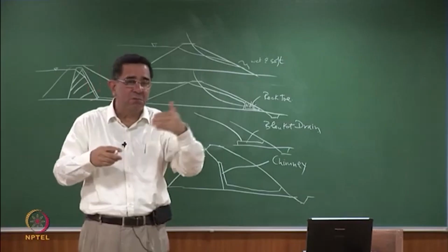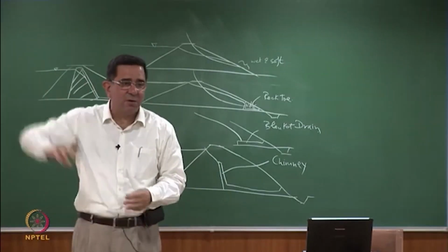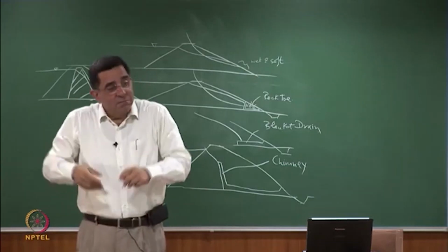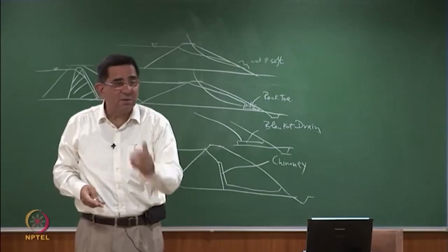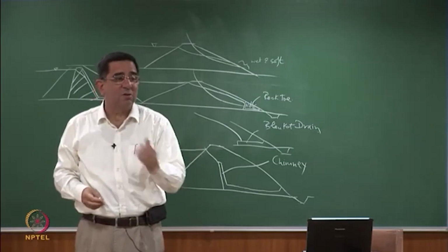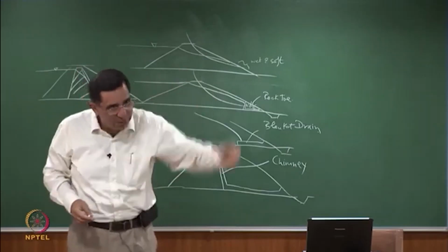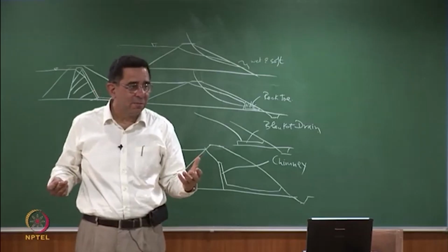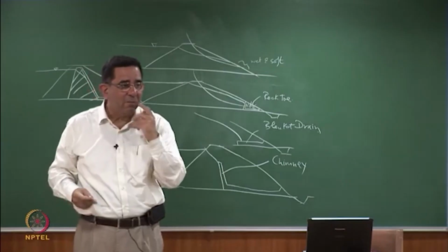The second issue being talked about is, if water is flowing underneath the embankment and is coming out on the downstream side, it can do piping, right? So how do we handle that? Flow beneath a weir is the ideal case to examine this problem. No water can go through the top of the weir, all water goes from underneath. So how do we tackle flow beneath a weir? How do we prevent the toe of the weir having a problem?